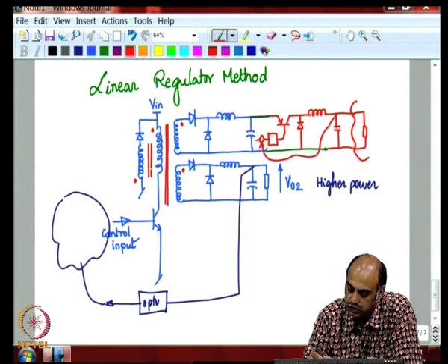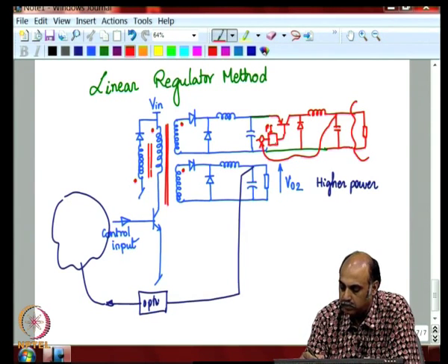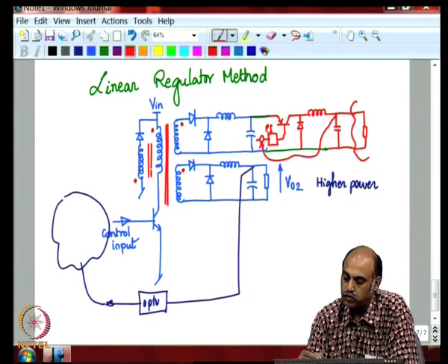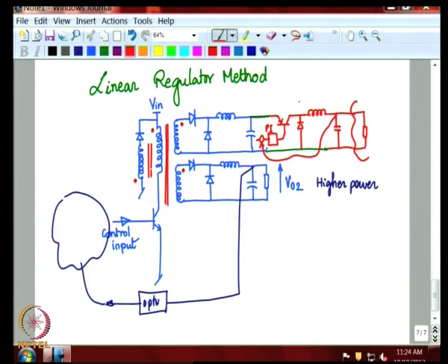So, this would be your PI, PWM and so on. This would be a local regulator based on TL494 or any other pulse width modulator, which is using the output voltage here itself as the power supply to power up this portion of the control circuitry.